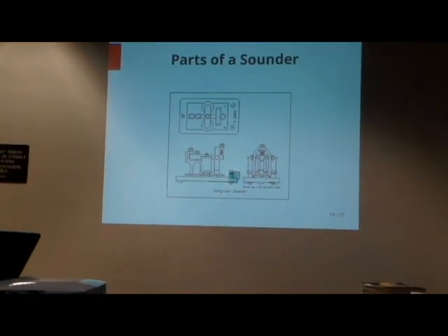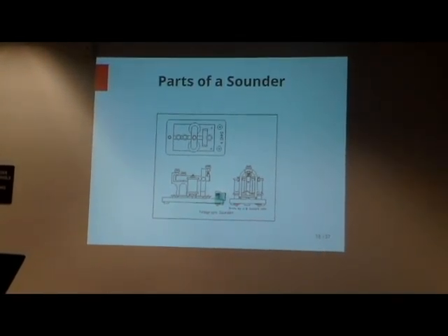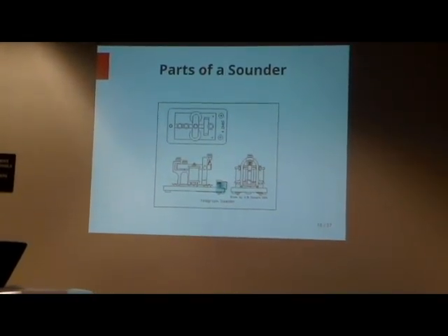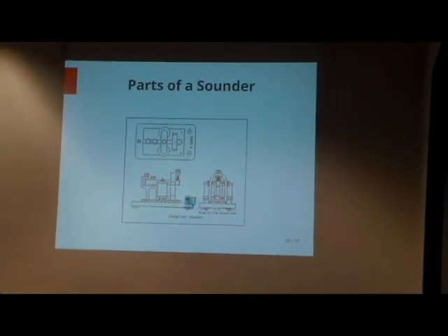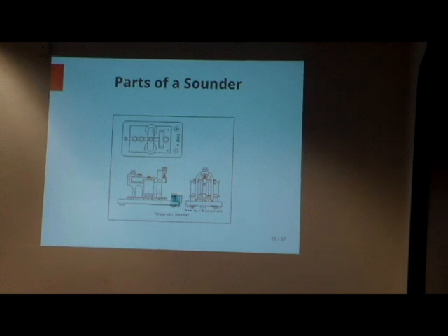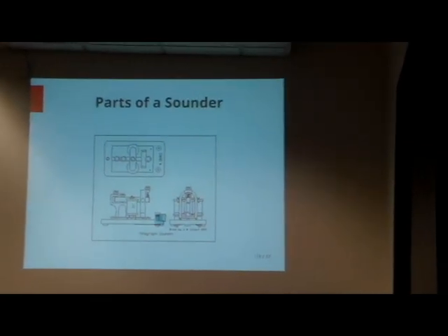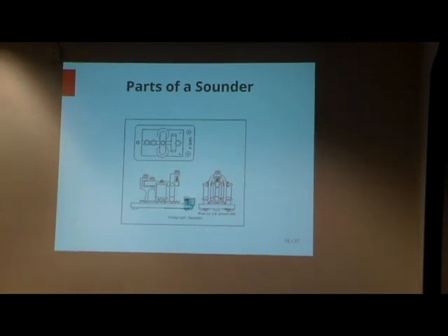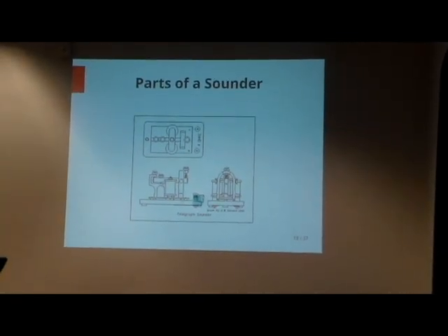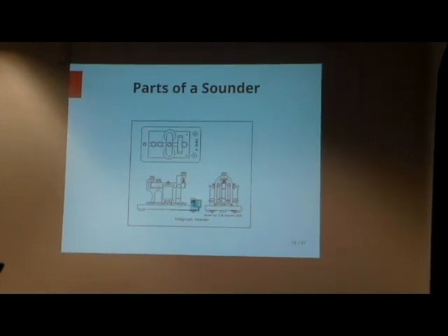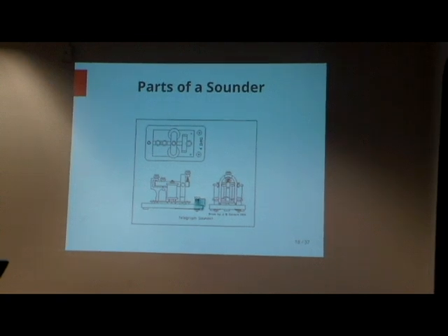Here's your return spring. Whenever the electromagnetic flux is absent, it throws the hammer up, making one kind of click. And when the electromagnetic flux returns, that pulls this iron bar, which you can see in the plan view here, down toward the magnets, and it falls to the limit set by the travel adjustment screw that you see the top of right there, and maybe you see the bottom of right here if your eyesight's real good.